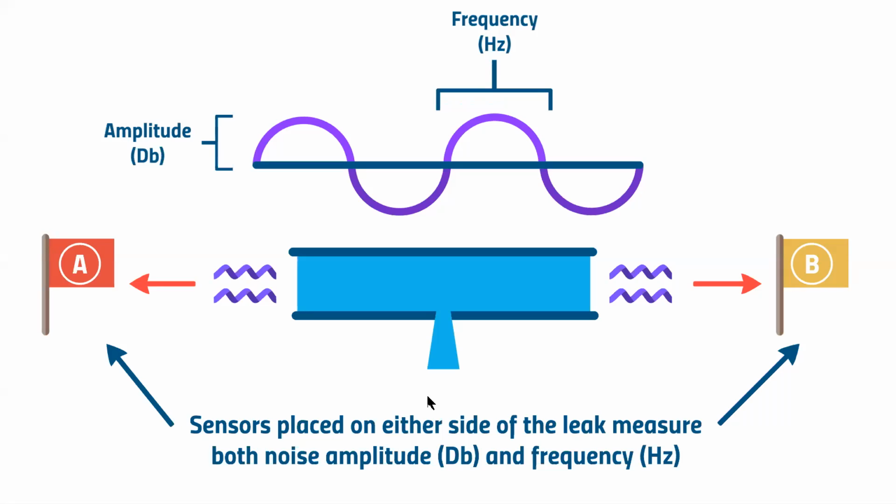The greater point is, yes, a change in pipe material and diameter in between two sensors isn't going to cause a problem as far as pinpointing the leak. But you, as the operator, the leak detector, need to provide the software, the processor, with that knowledge in order to accurately pinpoint your leak. So good question.